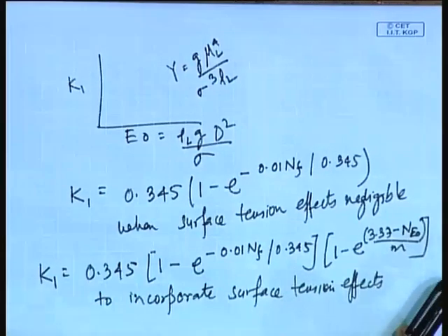But normally we do not use these analytical expressions; we prefer to use the graphs which I have already shown you. Using these graphs, if we know the Eotvos number and the liquid property group value, we can easily find u infinity. Once we find u infinity, considering the forces which are important, we can find alpha, and then the pressure drop and other things.